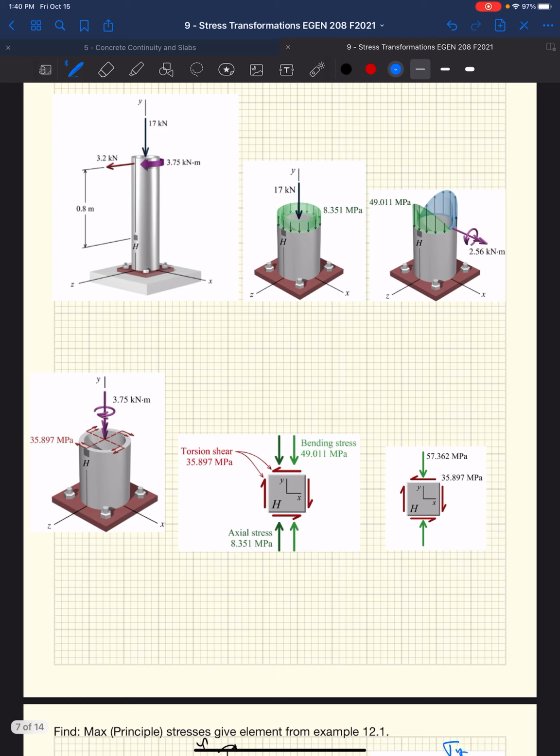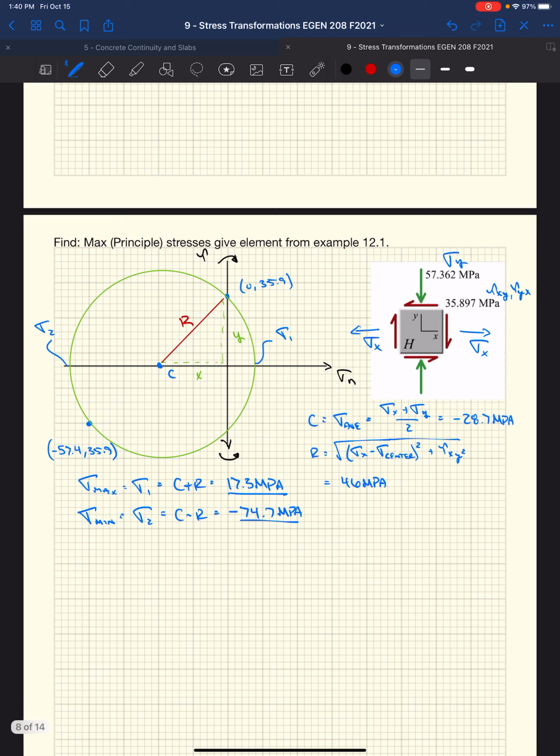We figured out our maximum shear stress based on the geometric properties of our pole, right? We've got max radius, we've got the polar moment of inertia. Bending stress, well, that's based on your moment of inertia and your cross section, which we'll get to. Then our normal stress due to the axial load, well, that was over area. So you'd run through this whole analysis, you'd figure out that the maximum tensile and compressive stresses are what